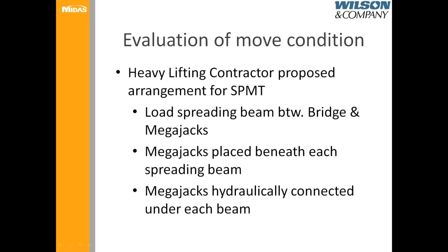Last thing I'll talk about was the evaluation of the move condition. The heavy lifting contractor proposed a certain arrangement for the SPMT equipment. This was shown towards the beginning of this webinar when we were looking at the geometry of the structure. So there's a load spreading beam placed between the bridge and the megajacks. The megajacks were placed beneath each of the spreading beams. The megajacks were hydraulically connected under each of the beams.